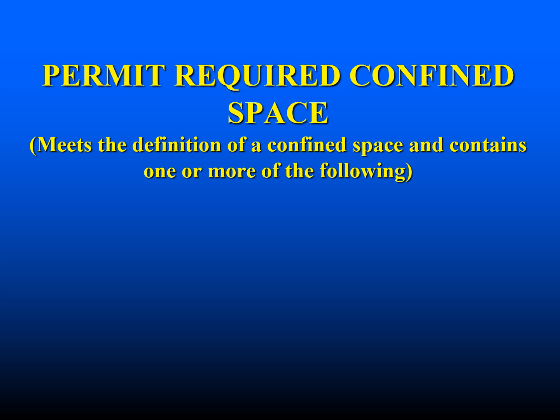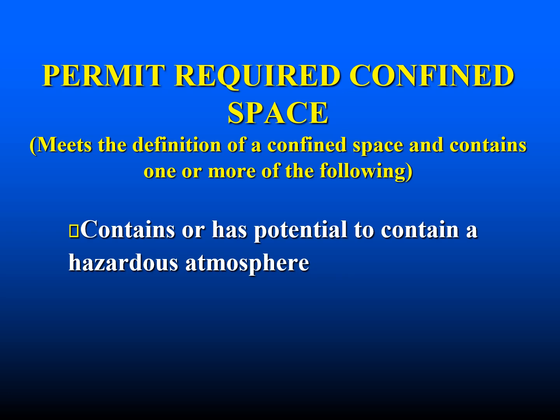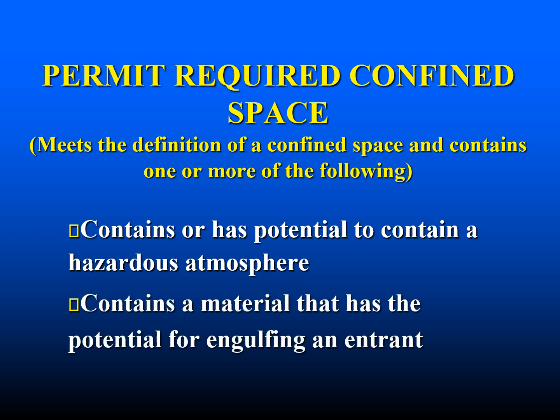Now let's take a look at a permit required confined space. It meets the definition of a confined space and contains one or more of the following. It would contain or has the potential to contain a hazardous atmosphere, contains a material that has the potential for engulfing an entrant,